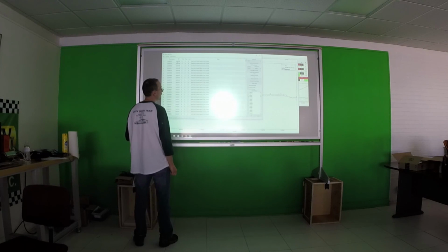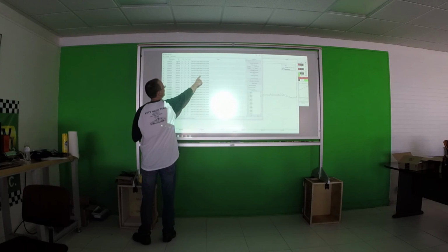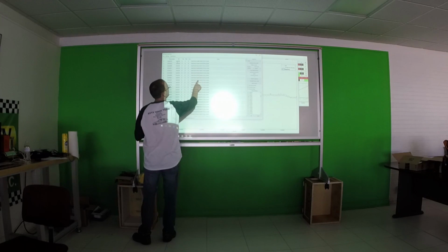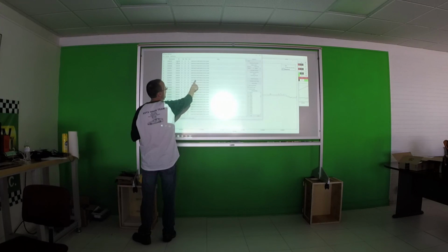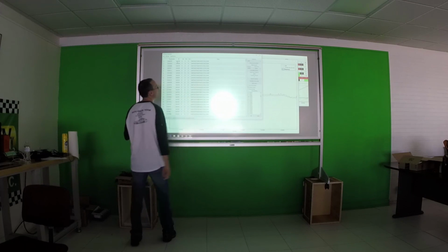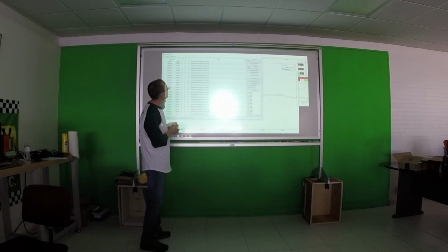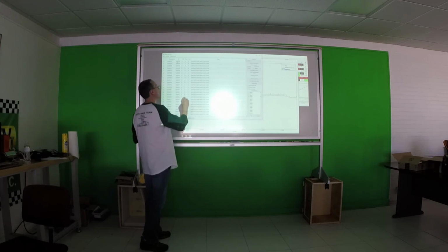And this program doesn't help me to crack that, but in a nutshell, what I would do is try to find a baseline, like say 0, 0, or a baseline 0 here where the counter is 0 and these are set as B2. I would look for 1 bit difference in the messages, which this is 1 bit different than this. Changed it to 7F instead of B2. What I would do then is take the exclusive OR of these two values and find out what happened when 1 bit changed in the message. And that would give me a value.